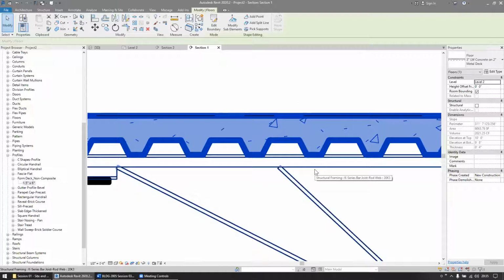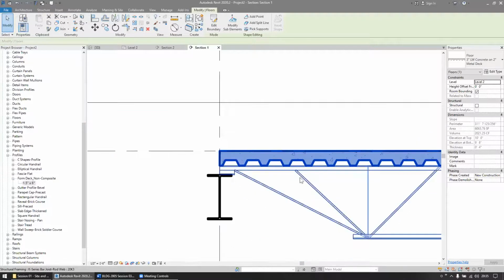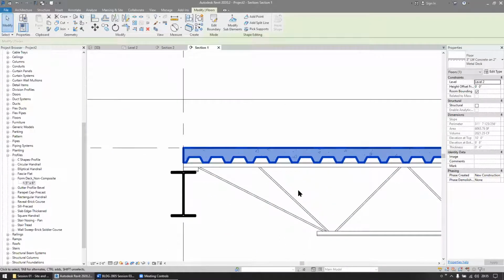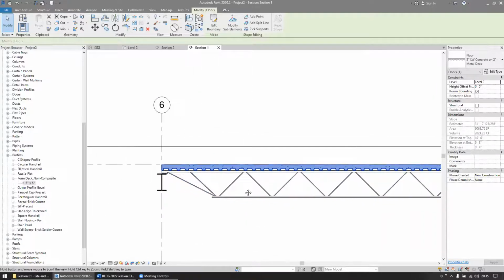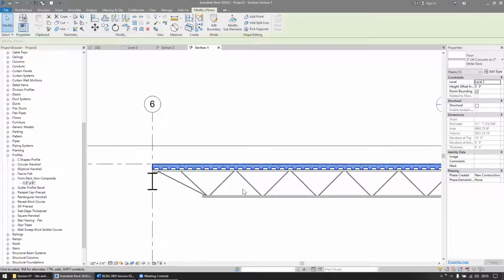I think there's a ULC rating for a lot of products that make steel decking for floors, and that gives you a 1 hour rating. So this 4-inch assembly with 1.5 inch steel deck is something you see quite a lot of in the Vancouver area, used for steel buildings.